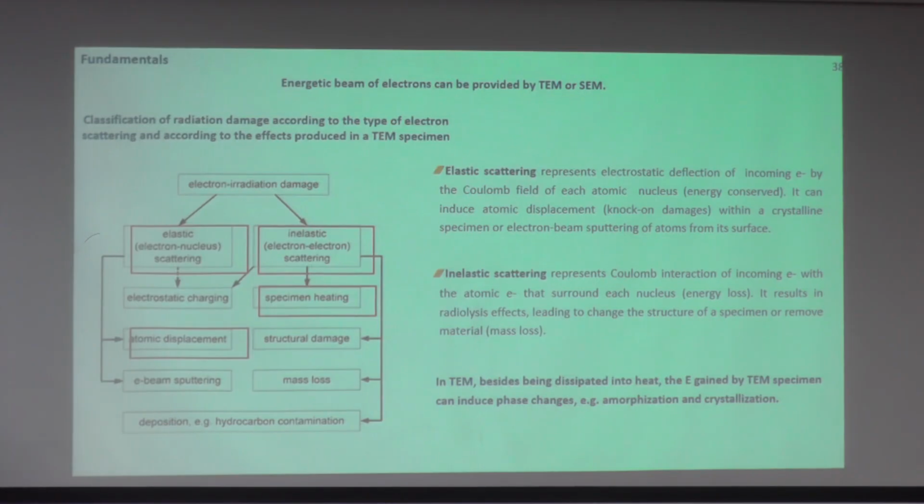Here, however, mainly we see in TEM the atomic displacement process and specimen heating. Structural damage is also present, but we will focus mainly on specimen heating and atomic displacement, and how to use these two effects to modify the properties of GST thin films.